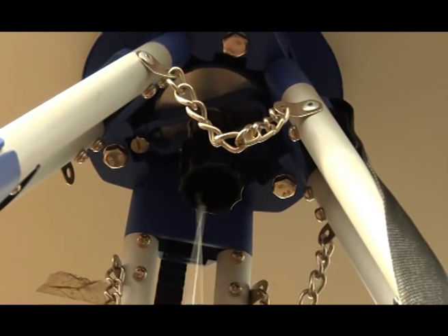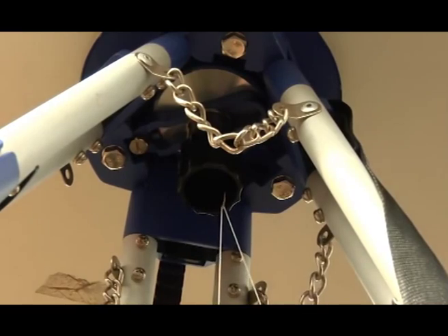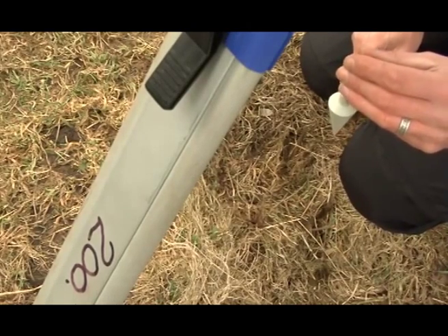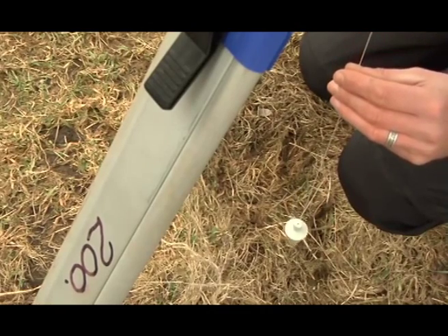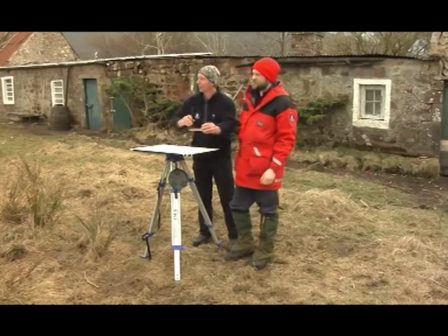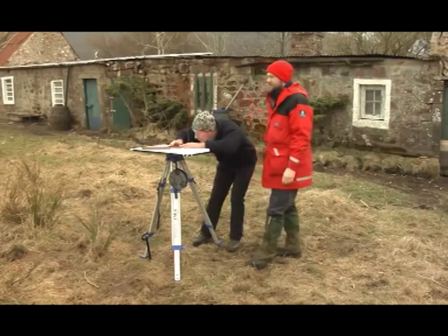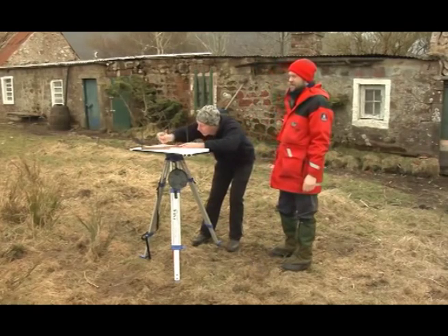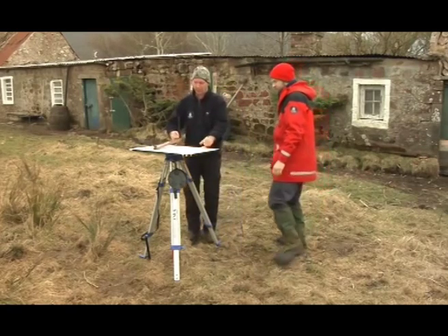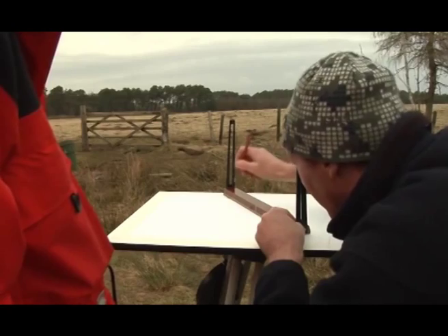The first thing will be to find out the height of the point where the table is placed. Therefore, a point of known height is first sighted and the height of the resected point where the table is fixed is thereby determined. Thereupon, other points are sighted and their heights are also determined. By means of the Indian clinometer, a ratio between the vertical height and the horizontal distance is calculated.